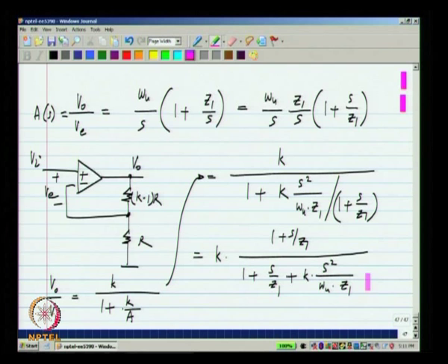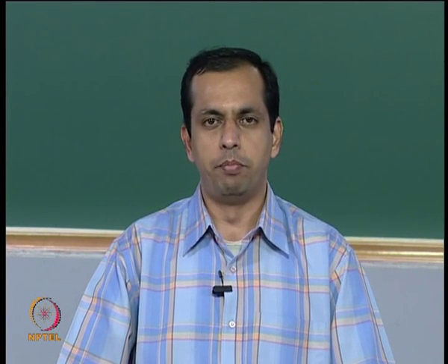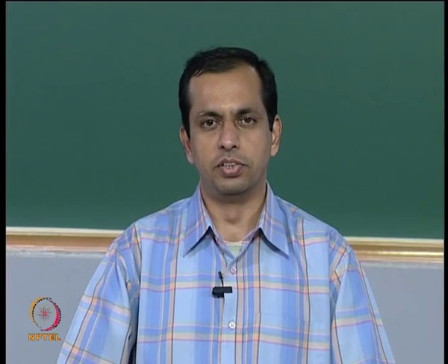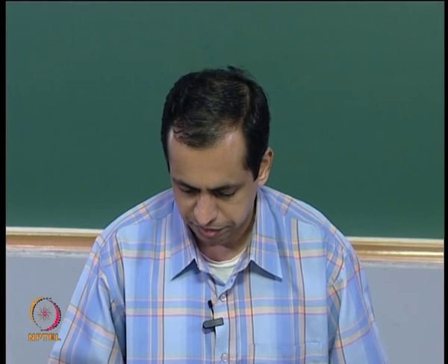Okay. Now, how did we evaluate such a case earlier? We looked at the damping factor or we can equivalently look at the quality factor and we saw whether the damping factor was appropriate, that is whether there would be a lot of ringing, whether the system was under damped, over damped or critically damped. Okay. We will do the same thing over here.